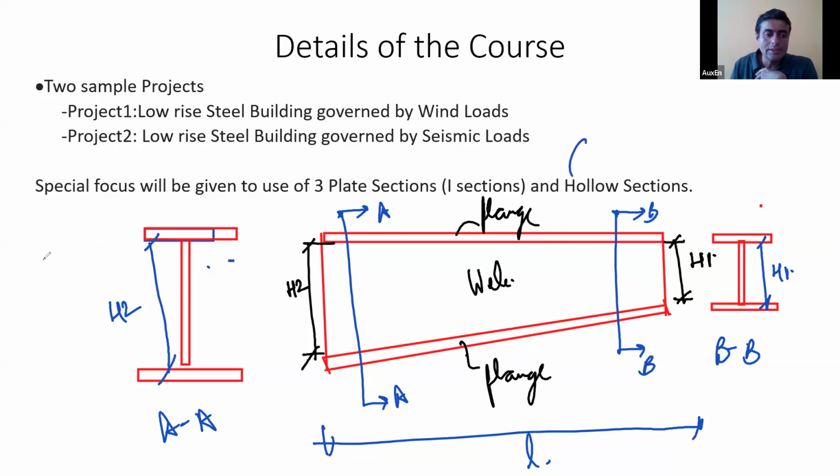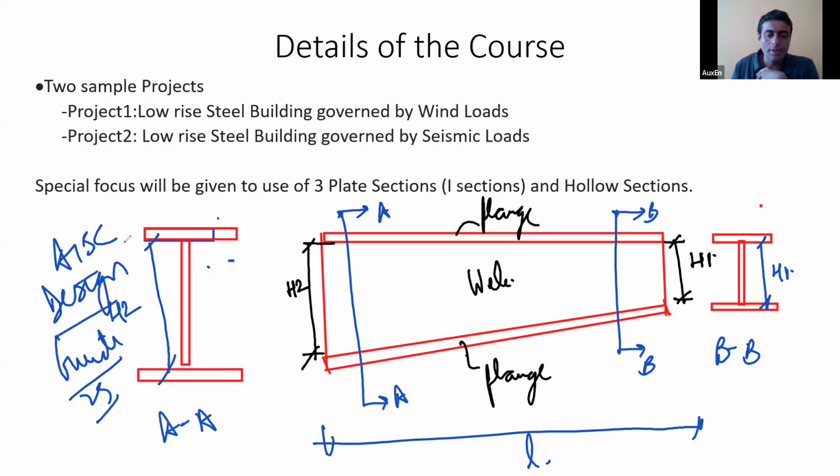And then there is this AISC Design Guide number 25. We will have a look at that later. But there is this AISC Design Guide number 25, which covers the web tapered sections. Clear? Design guides are like a small document of 15-20 pages, which focuses on a particular topic, and gives the structural engineer some tips and basic theory on that topic.